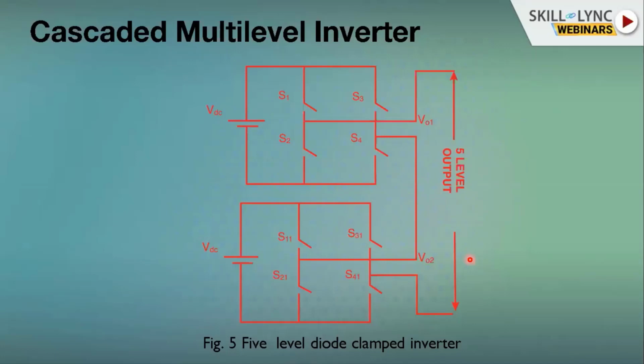The drawback that I see from this, or I guess all of you can say, is the number of switches, because they're all half bridge inverters, and the voltages add up in series. So what you'd basically do is connect the output of one, say for example the output of this, like this in a series fashion to the other inverter.